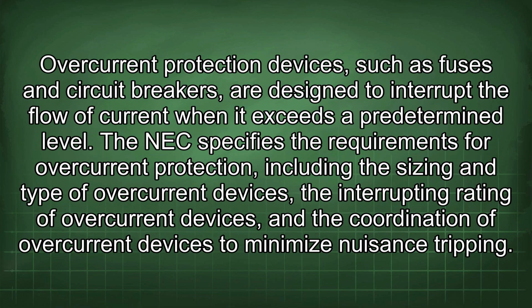Overcurrent protection devices, such as fuses and circuit breakers, are designed to interrupt the flow of current when it exceeds a predetermined level. The NEC specifies the requirements for overcurrent protection, including the sizing and type of overcurrent devices, the interrupting rating of overcurrent devices, and the coordination of overcurrent devices to minimize nuisance tripping.